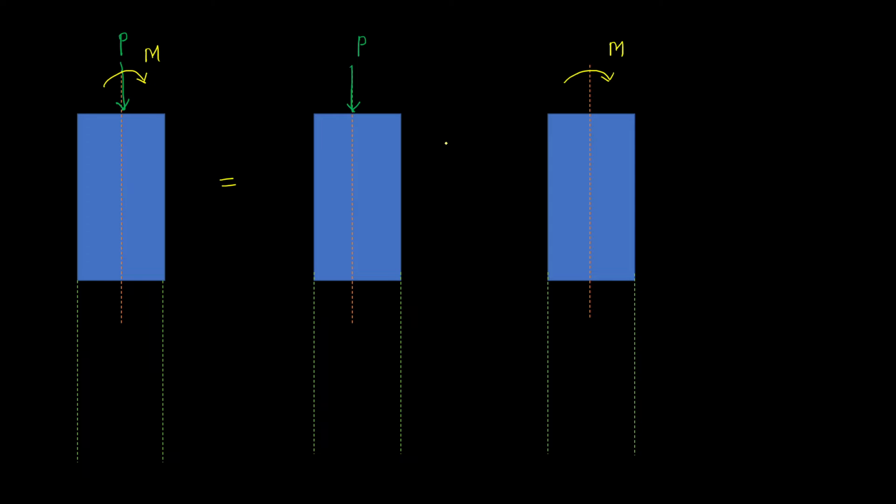So this method of separating a complex problem into two separate easy problems is defined as the principle of superposition. Okay, so we'll be seeing it in the third unit, that is in fixed beam. This principle we have to study in detail, but for now somewhere this is used, that's why I have recalled. So the total problem here, which is having a direct load and moment, is separately written as direct load plus a moment. So if we add these two cases, we'll get the final stresses.